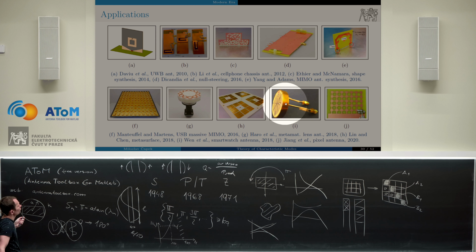So not currents, but voltages for all these local exciters. So with port characteristic modes, you get a significantly reduced algebraic problem. You still have orthogonal far fields and all the good properties of characteristic modes, and you have a prescription of how to realize and how to excite this port characteristic mode directly. So a lot of advantages to think about this possibility.